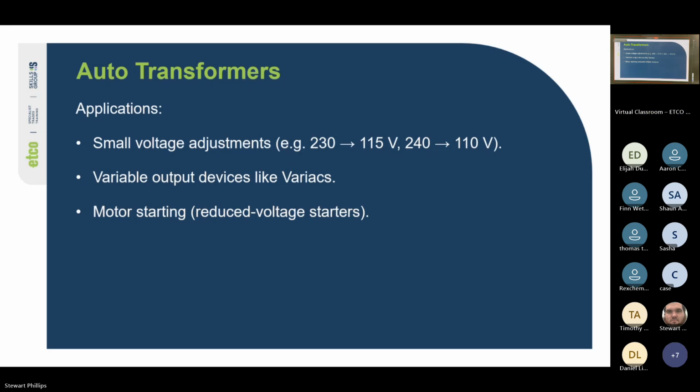So they had two options: either buy a really fancy device to do the work, like an auto transformer, or rectify it to DC and then use an inverter, or replace the motor inside the mixer. I'm not sure what they did. I haven't seen them since. I have to find out about that.